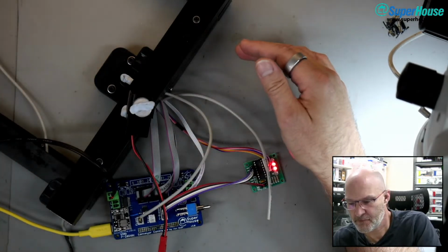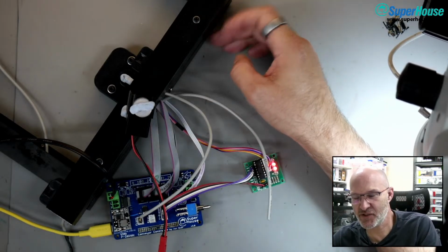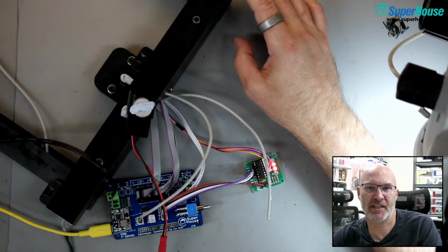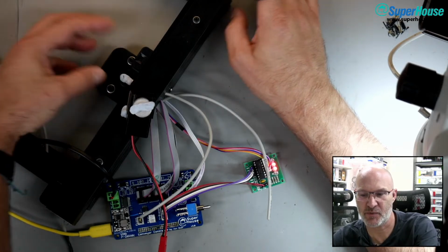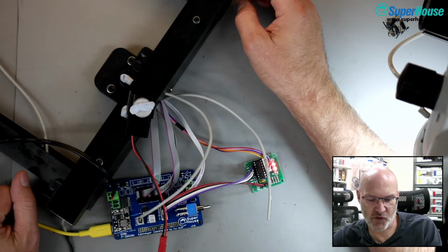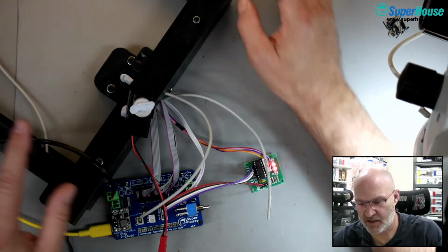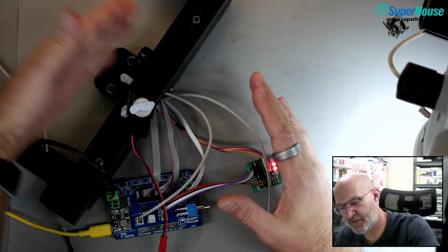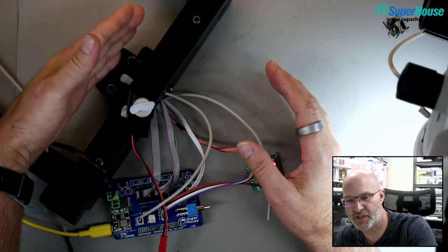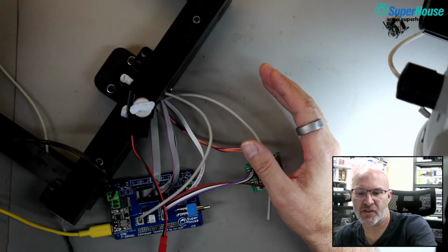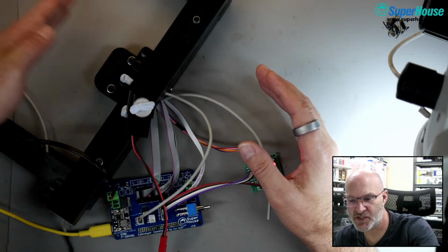Add a breakable joint in the belt or slipping. Yeah, all of these things could be done, but I just don't think they're necessary, because I think slipping on this will save it. So, yeah, it doesn't matter. I understand that having it crash into the front is a potential problem because it's open loop at that point. It homes and then it goes open loop and it just counts steps to move to whatever the target position is.